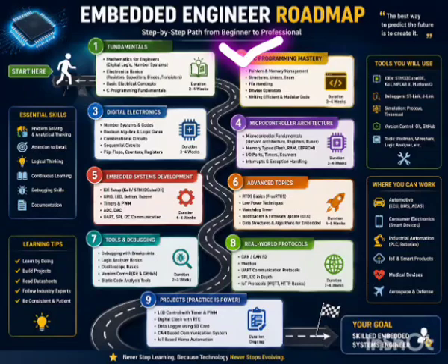And step 3, learn microcontrollers. Now move to microcontrollers. I recommend boards like STM32, ESP32, Arduino. Understand GPIO, timers, interrupts, ADC, what is a timer, what is PWM, what is UART, how these communication protocols work. So you need to gain an understanding of microcontrollers and related peripherals and communication protocols as well.